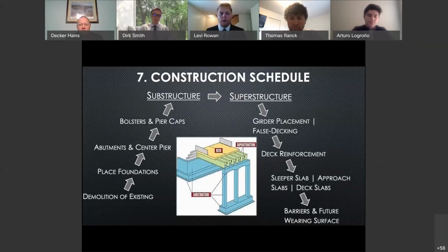It is important to note that the detailed schedule depicts separate construction of the east abutment, the west abutment, and then the center pier. During the final stages of concrete placement, bolsters and a center pier cap are included. The early stages of the superstructure must follow proper lane closure methodology. The east girders are erected, then the west.